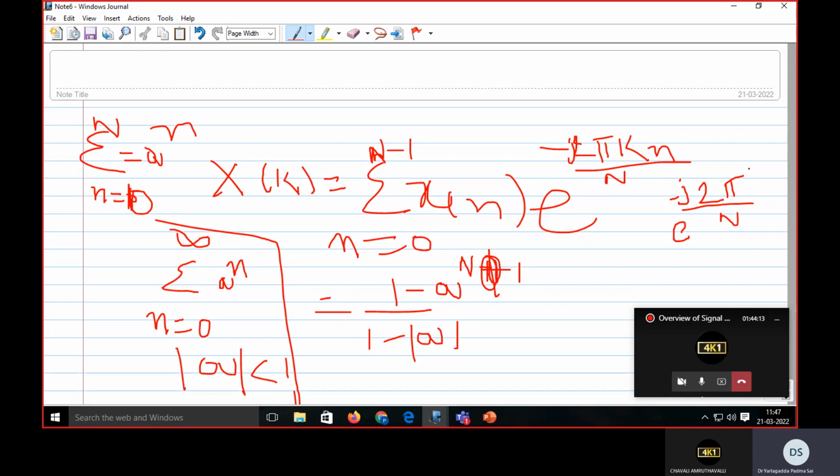Okay, so when we are evaluating DFT directly, we are not using properties of the twiddle factor. But FFT algorithms have two properties: one is the symmetry property, another is the periodicity property. Because of using these two properties, it is able to reduce the number of multiplications and additions drastically to n log n, or n by 2 log n, compared to n square, n into n minus 1.